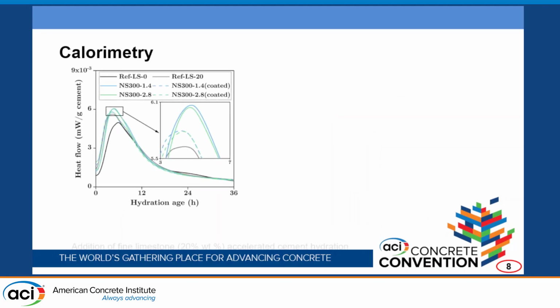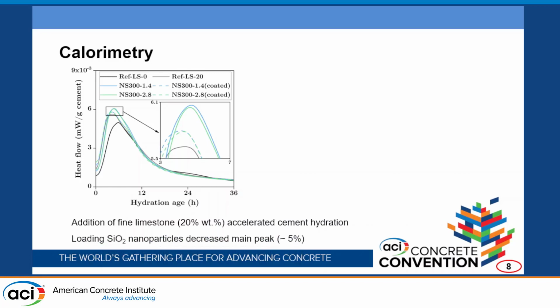We also did calorimetry to check the kinetics of cement hydration. We can see that the addition of the fine limestone that we use accelerated cement hydration, as expected. The loading of nanoparticles also decreased the main peak, as you can see here, maybe statistically insignificant.